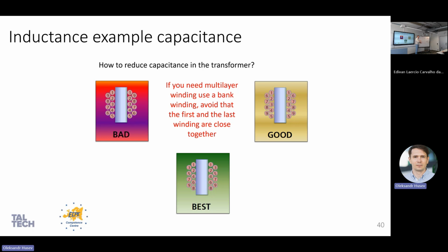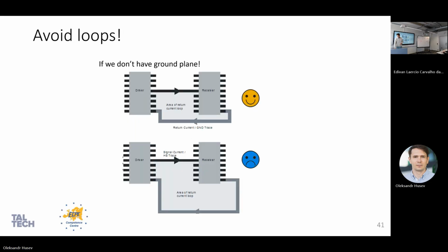But in case of modern devices, like megahertz switching and so on, any small parasitic capacitance is already sizable compared to what you may have in your datasheet parameters. Right? And once again, this PCB design costs nothing for you in terms of extra cost for your product, right? So about inductance and capacitors mostly over. Now how to minimize or to use it wisely in your design.